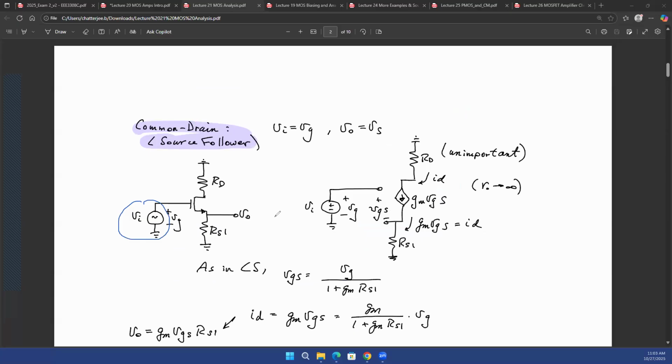So to find out the effective output resistance, you just have to get rid of this independent voltage source. That means short the voltage source to ground. That's what you'll need to do. So your input voltage source needs to be connected to ground. And at the output, you can connect either a voltage source or a current source and find out the other quantity, and the ratio of voltage to current will give you the resistance. Okay? Same as finding any Thevenin equivalent resistance. So let's do that now.